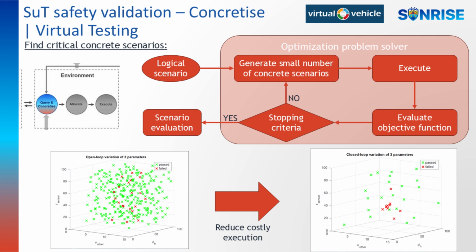In the next example, guided search of a logical scenario's safety-critical parameter combinations was used to reduce the overall effort for testing significantly. By constructing an objective function as a numerical representation of relevant metrics like time to collision and inter-object distance, a constrained optimization problem is formulated.